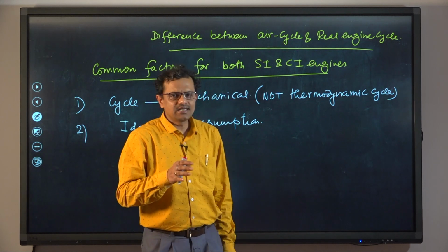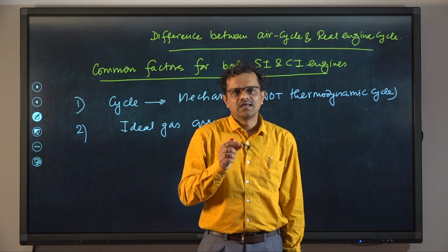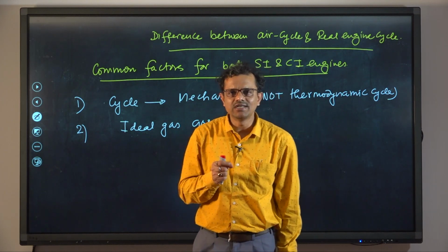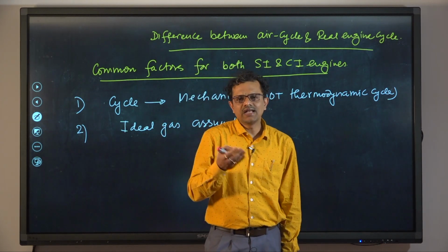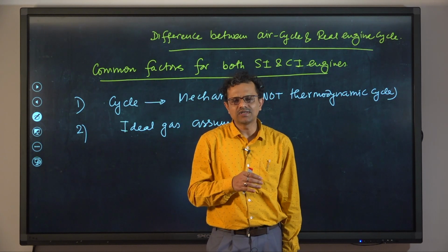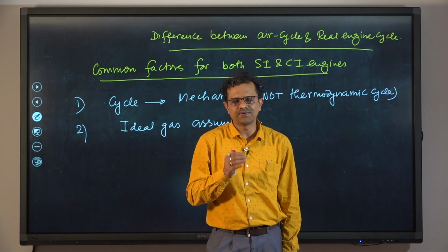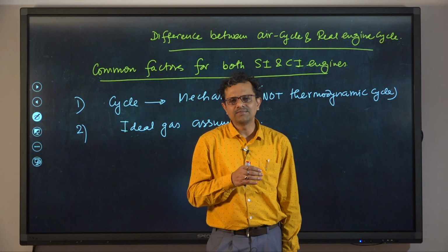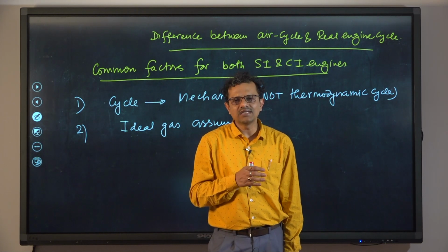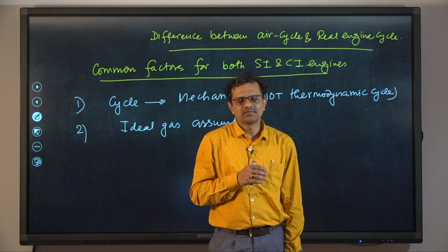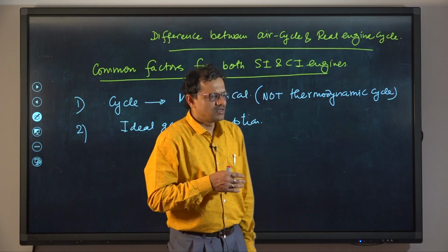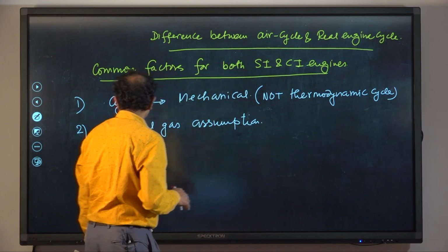But as I said, considering the air-fuel mixture which is drawn into the engine cylinder during the intake stroke to be an ideal gas is still okay, because 91% or 92%, depending upon the requirement, is fresh air, while the remaining 7% or 8% is fuel. So, it is still okay, but combustion gases cannot be treated as an ideal gas. So, this is important.